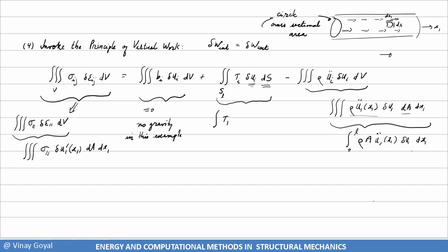So then I have this integral. So this ds is really dx1. And then the circumferential direction is ds. And let's presume that the traction is constant around the circumference, but it can vary in the x direction. So in other words, this traction Q only varies in the x1 direction, but not around the circumference. It's constant around the circumference, which is totally a good assumption.